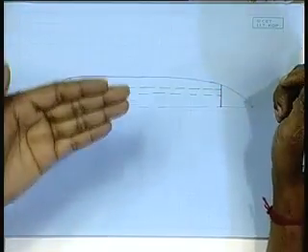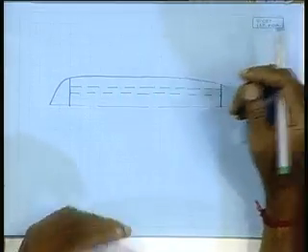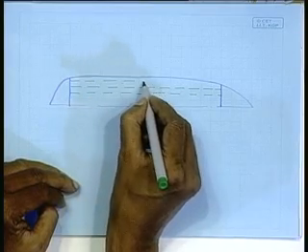So, to provide for required buckling strength, I will have to provide for additional scantlings, higher scantlings, additional longitudinal members probably. You have the transverses, higher longitudinal members. So, eventually the structure would have been inferior from the strength to weight ratio point of view. So, in that case, we will rather prefer a longitudinal stiffening arrangement like this.